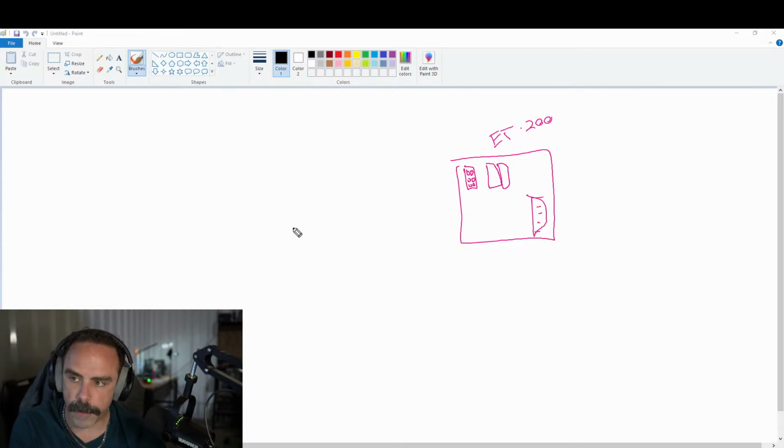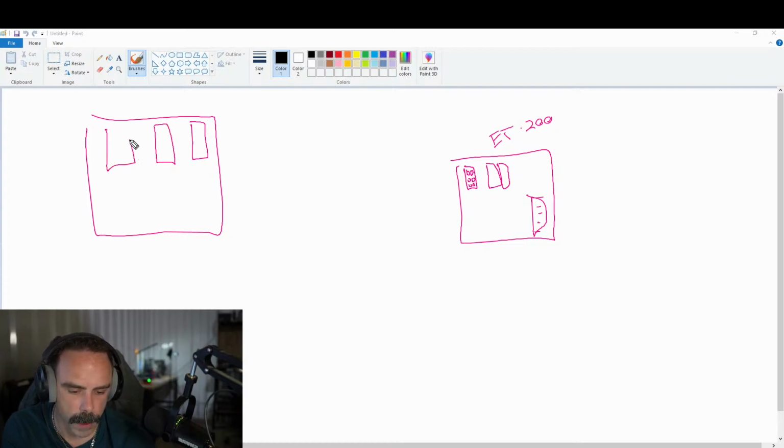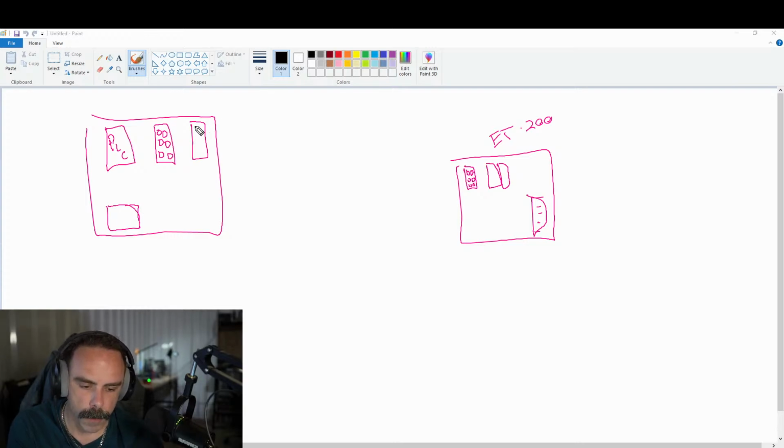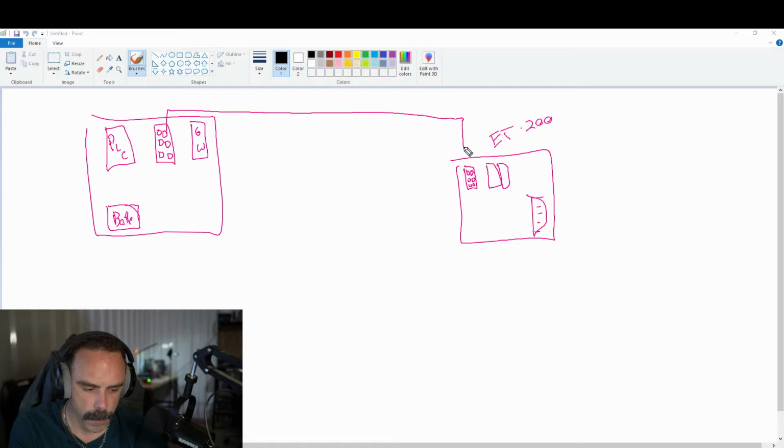And then, making sure that I don't block this up, another thing is usually our gateway switch with some fiber ports or something, and then our PLC, battery backup. So PLC, then a switch. And again, we'll configure this here in a second. And then maybe this is our gateway. And then this is like battery backup. And then we would bring one of these here.